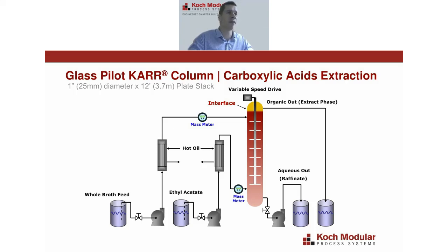We do that all the time. The plate stack was 12 feet high. Besides that, it's essentially the same as the slide I showed earlier. However, the one difference here is that the solvent is dispersed and the feed's continuous. So here is an example where we're taking advantage of the Marangoni effect, with the mass transfer going from the continuous feed to the dispersed solvent.